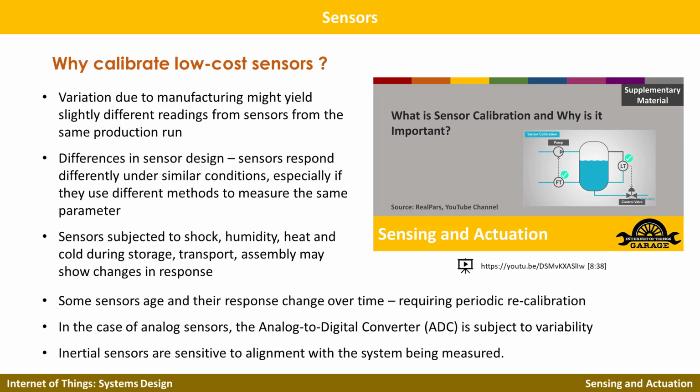If it is something like smart home monitoring, of course you can do this kind of adding of Celsius. But if you are doing precise measurements, or where more damage would happen, like measuring the temperature of medicine storage, then you should not trust just adding a couple of Celsius to the sensor readings at the software layer.